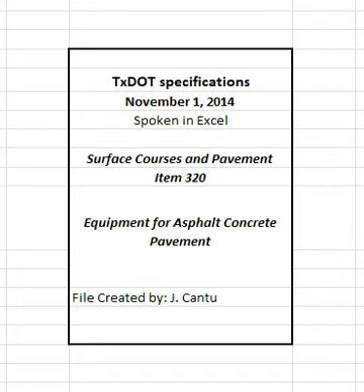2.1.2.2 Aggregate weigh box and batching scales. Provide a weigh box and batching scales to hold and weigh a complete batch of aggregate. Provide an automatic proportioning system with low bin indicators that automatically stop when material level in any bin is not enough to complete the batch.